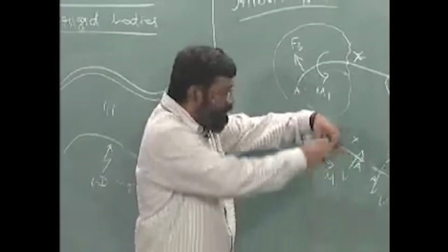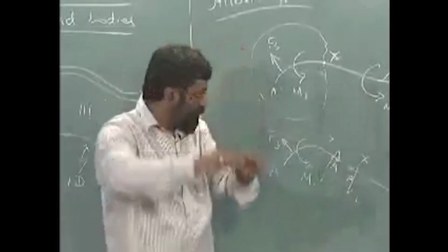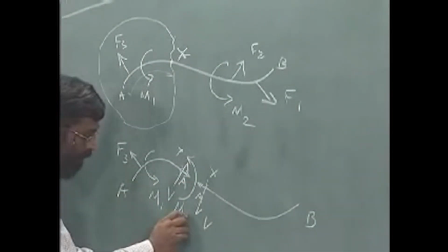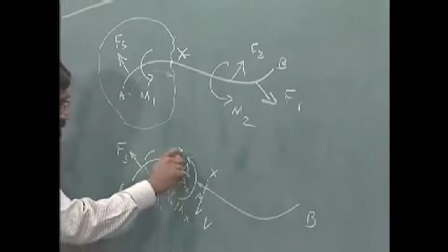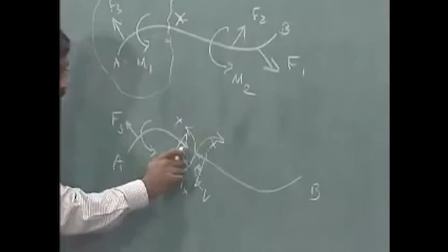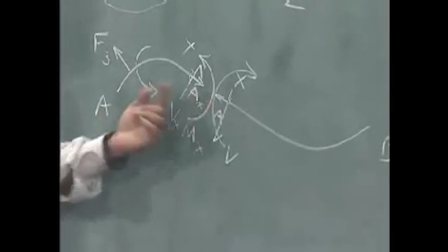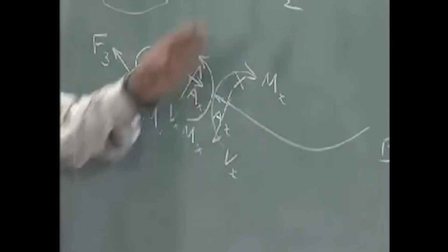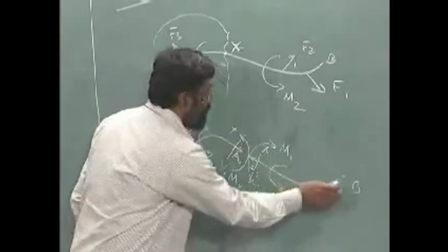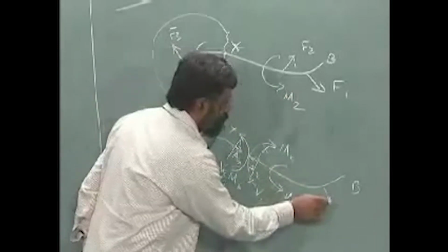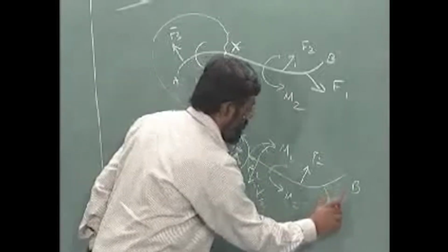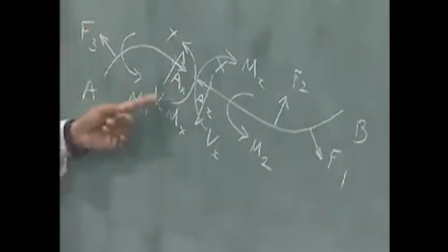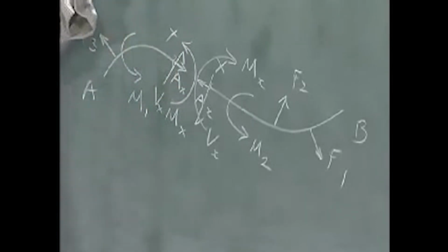It could also be resisting, for example this is resisting bending. So there could be a resistance in bending and that could form a moment, all at x. So I am going to use a suffix x in all this. Equal and opposite moments occur because there are reactions here that will cancel each other. Now I can insert all the other rest of the forces that act on this particular body. As you can see here, there are three internal force resultants that appear upon sectioning at x.